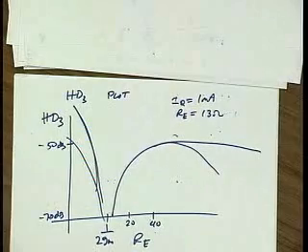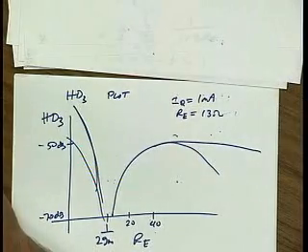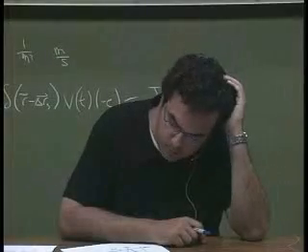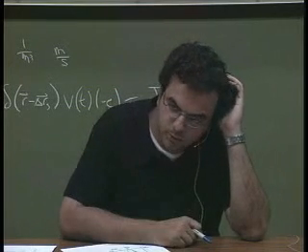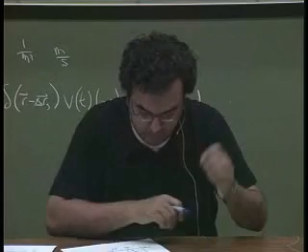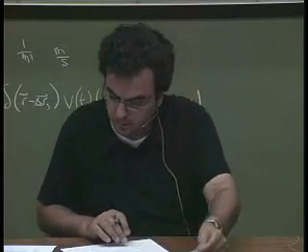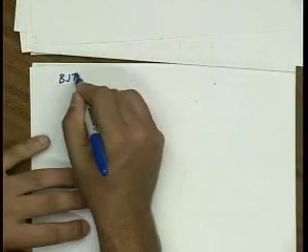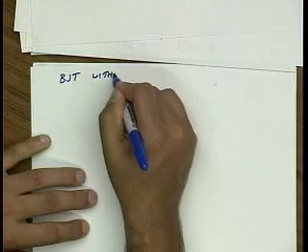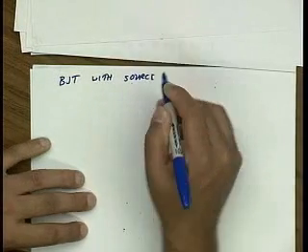Question? Can't you do the RE with some kind of a diode connected BJT over there, because then you will get your temperature matching and so on? That's what people do. Yeah. If you ever look at schematics of op-amps and things like that, you see weird diodes hooked up to the emitters, and you wonder, why are they putting diodes in the emitters? Well, that's the answer.